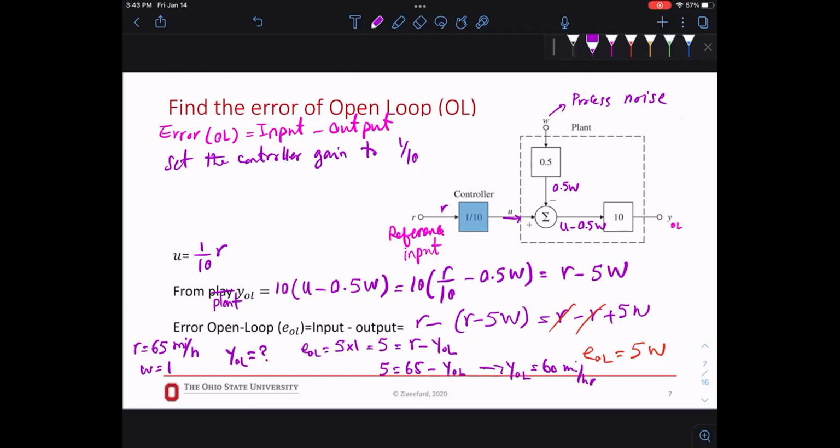So this is good, it gives you an idea. If you're designing a controller, you want to decide if it should be open loop or closed loop. You can check it for a couple of scenarios that can happen, check your error, and get the percentage. If it's below 1% and you're happy with below 1%, you don't design anything after. Open loop is good enough for you.